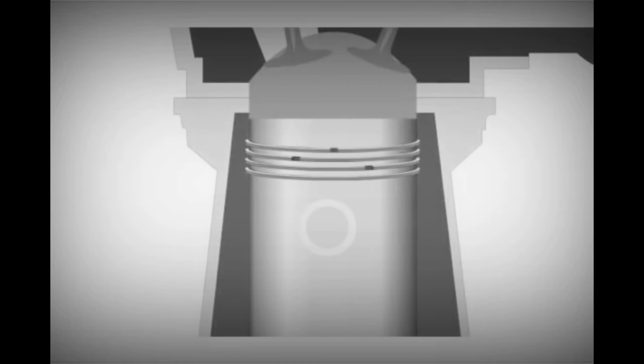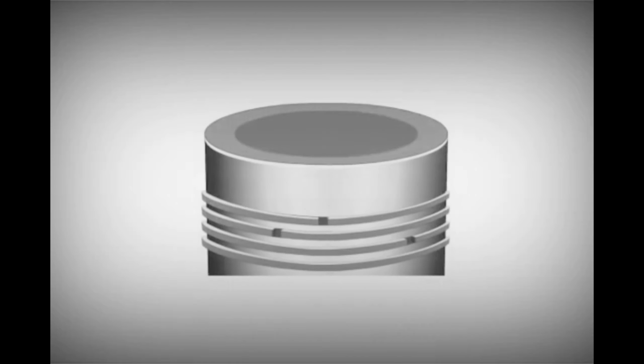If the clearance is greater than the maximum limit, combustion gases blow by the rings and exhaust gases enter the crankcase. This results in loss of compression pressure in the cylinder. To measure butt clearance, insert the rings in the bottom of the liner and ensure that they are in line with the liner axis. Measure the clearance between the faces of the piston ring using a feeler gauge. Record two sets of readings, forward-aft and port-starboard.